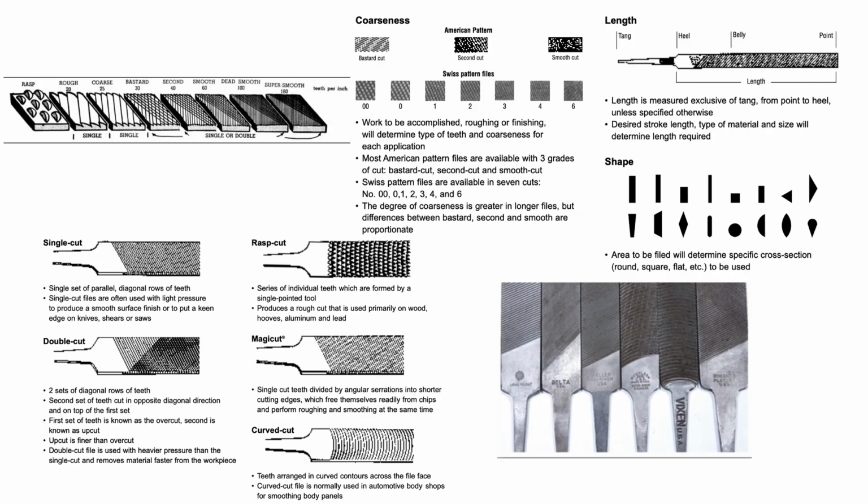Also rasp cut file, it has very sharp and very big teeth, so thick teeth basically. These teeth are triangular shape and are in bulging state. It is used for jobs of wood, plastic fibers, and hard rubber, and jobs of horns and hoof of animals. We don't deal with it, but this is just for information. I mentioned the details of the surfaces of the file.